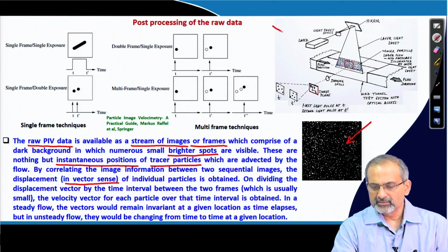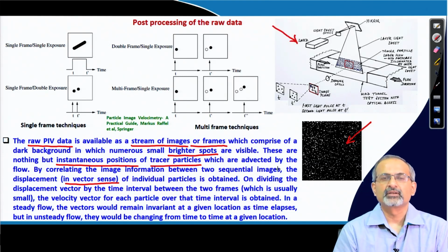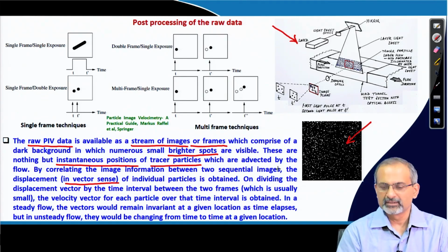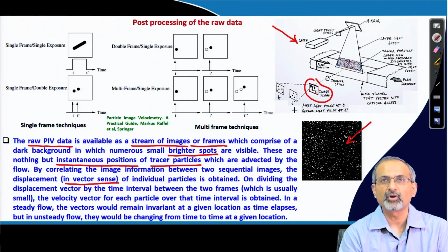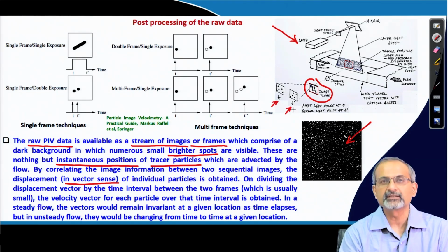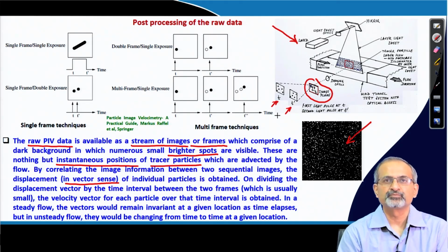We recall this small sketch that we had looked at the beginning of the lecture, which initiated the section on particle image velocimetry. There we had talked about the entire image plane and then trying to break it down into small sections called interrogation windows, and looking at the interrogation windows at different instants of time and trying to figure out the particle movement by referring to two juxtaposed frames.